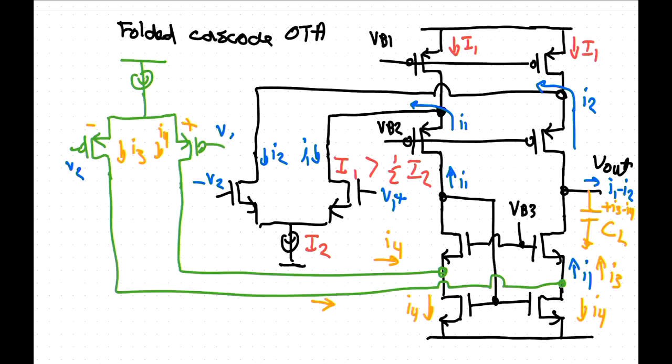Is V1 bigger than V2 on the first pair? I think that's right. Yeah. So if you swap them around, they cancel at the output and the gain is 0. So you just got to make sure that you work out the right way. So rail-to-rail input, which is another really useful thing.